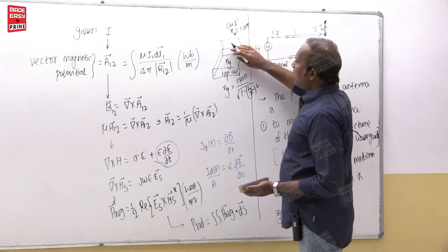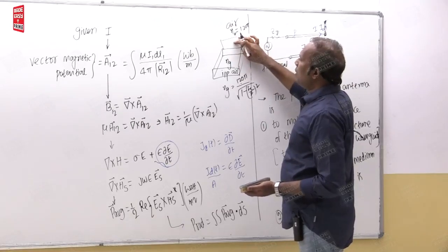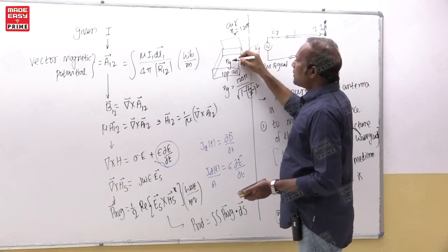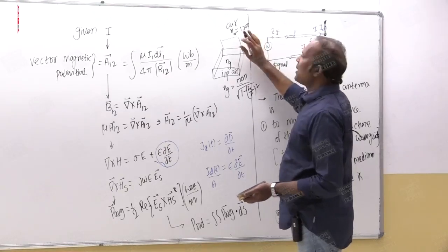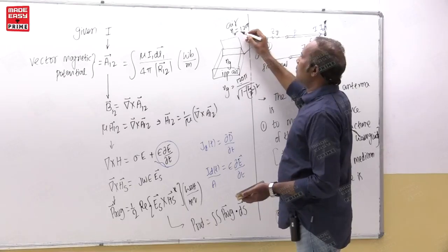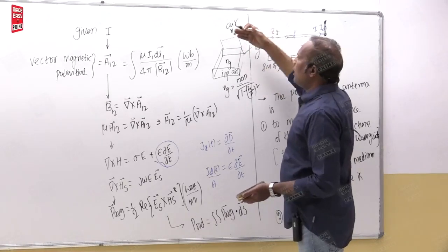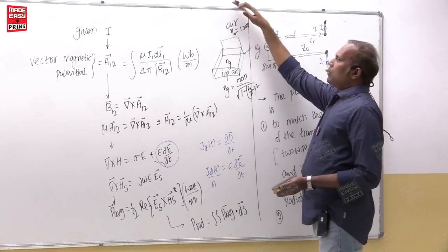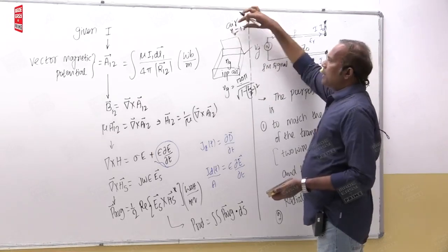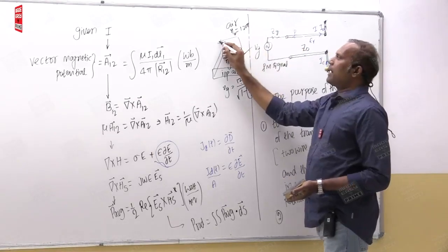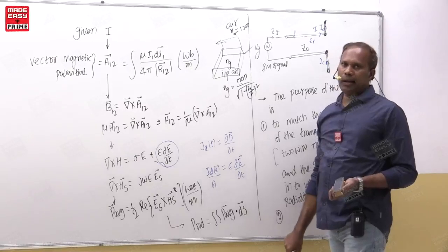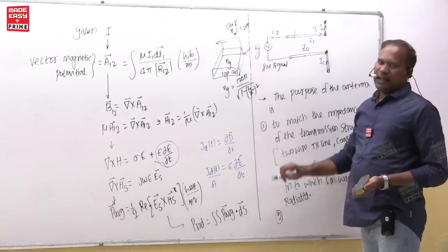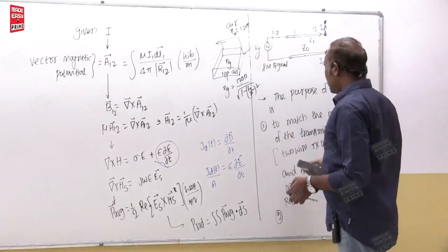As you keep opening the ends, whenever the impedance of this waveguide due to change of dimensions approaches this 120 pi, the waveguide dimension is cut there, so it easily matches this impedance and that impedance. Now this is called a horn antenna. So impedance matching is done.